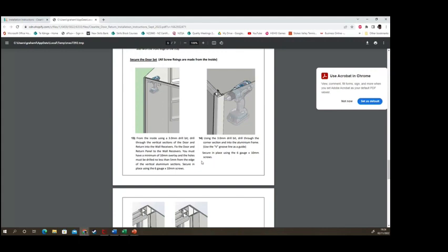They can be a little bit out because the walls are out and the floor's out. I think that's happening in my house now. The shower there's like a gap between the tray and the curtain. It's a bit funny because typically the way they're set up is that the tray goes in and they jib around the tray. So the tray sits flush to the frame and then the jib overhangs 10mm. Then sometimes there's a little bit of a cavity there, and that's where the white silicone goes to seal up the whole bottom of the tray. So it's only really got that 25-30mm bead of white silicone to seal it all up.